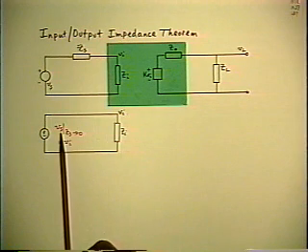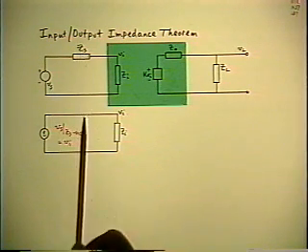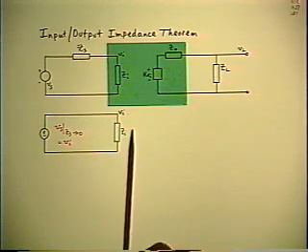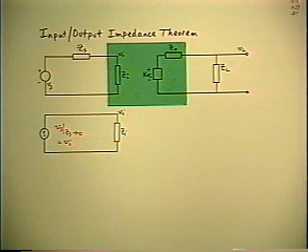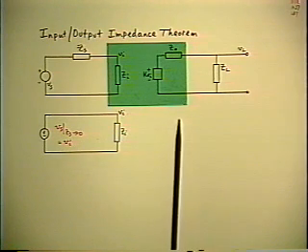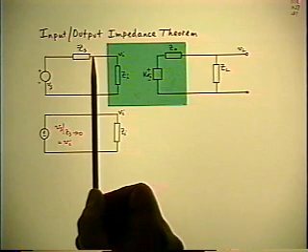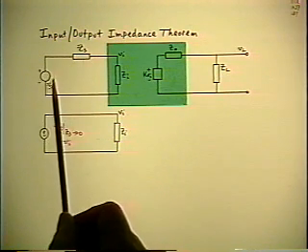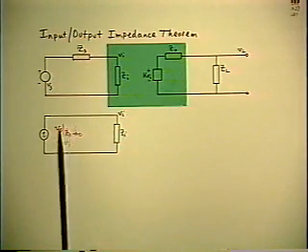And again, this is to introduce notation. Vs under the condition of Zs going to 0 is simply the notation that says that's the input voltage you need. And of course it's equal to the VI that you want to get. Then you go to the opposite extreme. Visualize replacing the Thevenin source equivalent by a Norton equivalent, which would be a current generator, Vs over Zs, in parallel with Zs. That's the Norton equivalent.